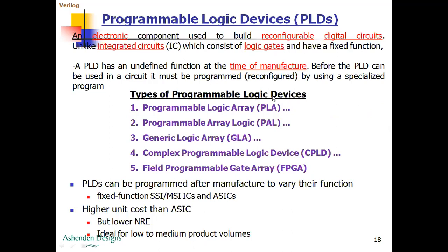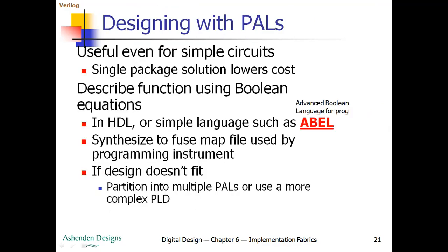These PALs belong to the family of PLDs, semiconductors used to implement logic functions in a digital circuit. So you can say PALs are one kind of programmable logic device, and they have a programmable AND plane and a fixed OR plane.